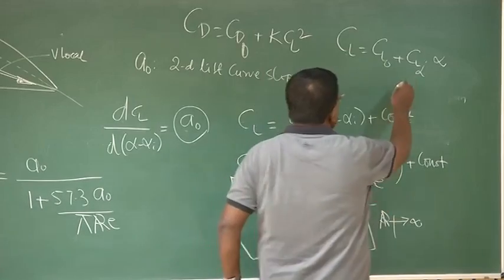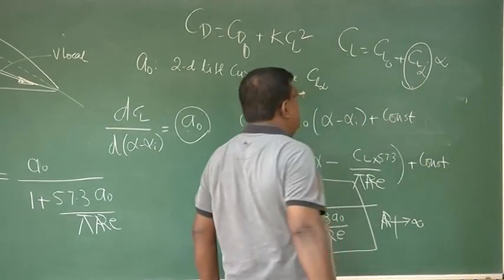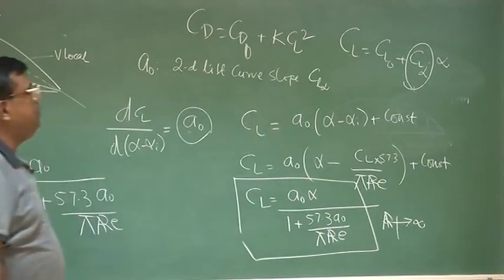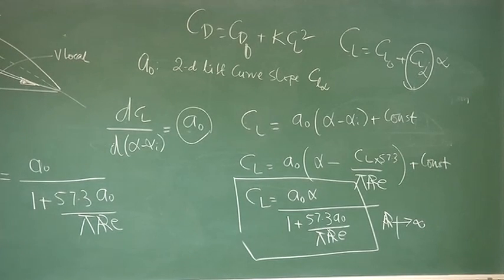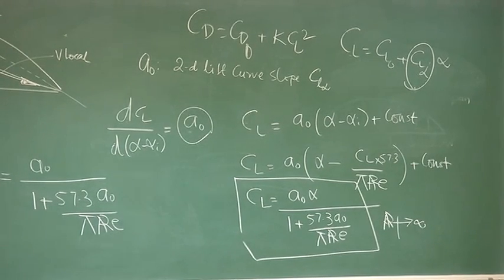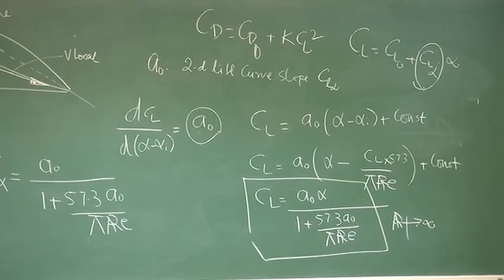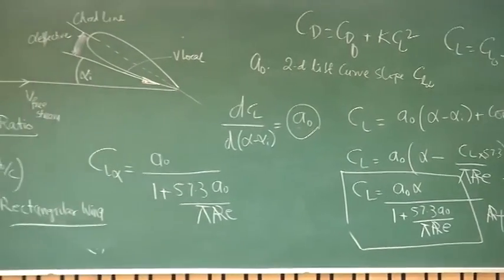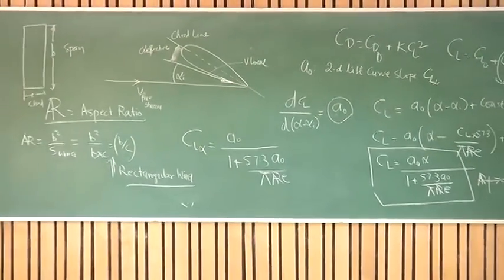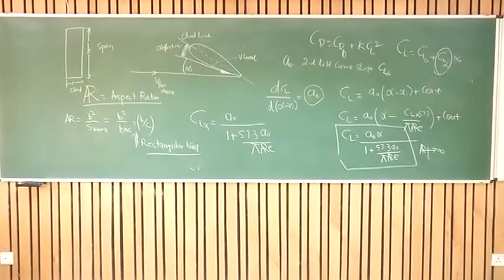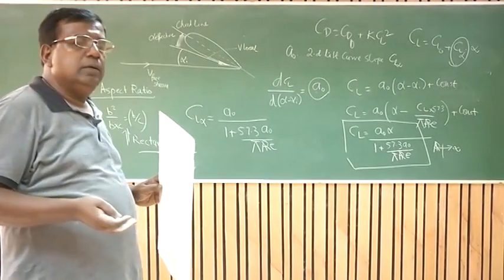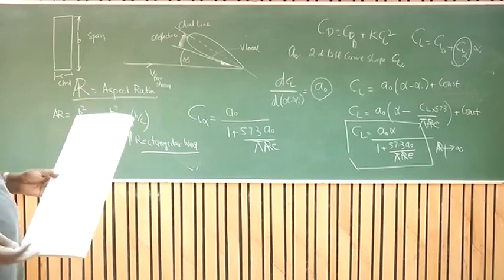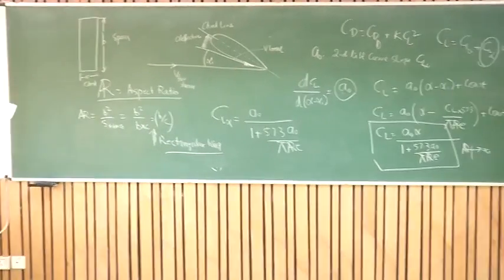And for the finite wing, we were trying to understand with aspect ratio how the CL alpha of the wing is going to change, right? So this is good enough understanding for us to use for performance analysis. Most likely, we are going to start with the cruise performance next.